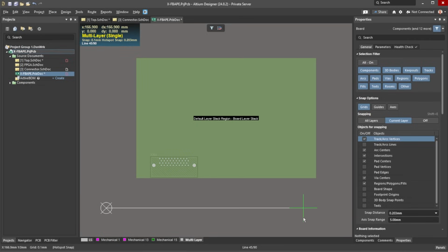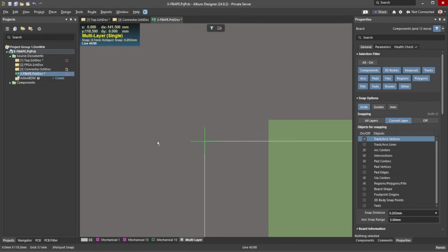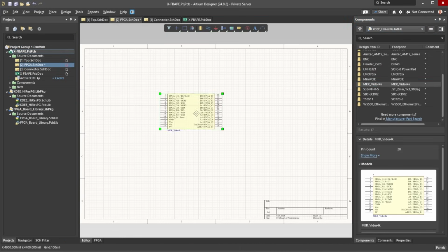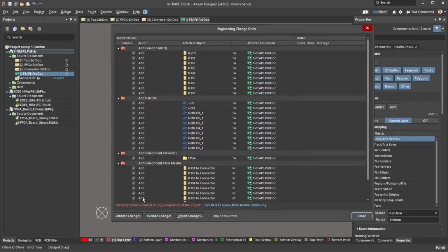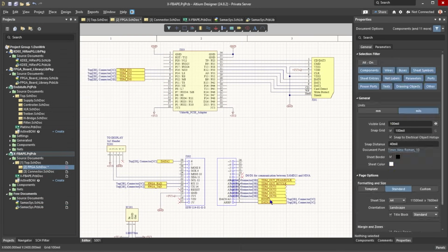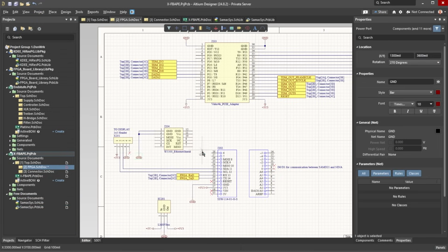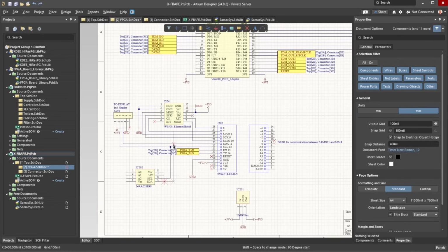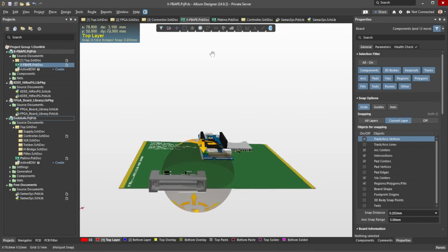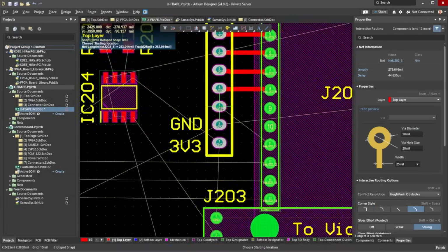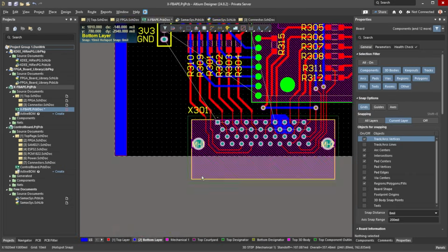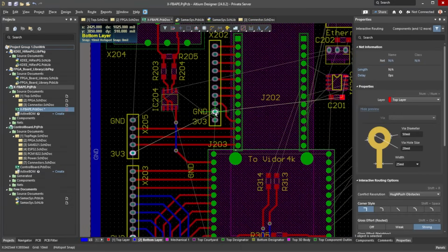But first of all, we now need to specify the basic dimensions of the circuit board and position the connection to the X32 correctly. Now we put all the components we want to use on the circuit diagram. In addition to the connections, this also includes a 3.3 volt voltage converter. As I want to use the USB connection of the WiDAR 4000 without opening the X32, only one direction of this board remains. So we place the WiDAR 4000, the SD card and the XLR connector before we route the tracks. As with the original boards, I provided a ground plane on the left and right to ensure good grounding between the housing of the mixing console and the expansion card.